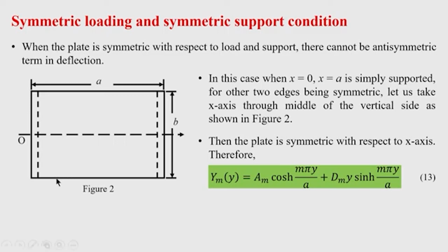For example, a slab culvert, you have seen the slab culvert, okay, or slab bridge. A slab bridge is also there for small span, where only the slab is resting on the abutment. So, in that case you can see that these are the abutment supports. So, it is supporting the slab on the two opposite edges just like a simple support, and the other two edges are free if there is no stiffening beam or girder. So, then these two edges are free. So, this condition may also represent a slab bridge supported by abutments at the two ends.